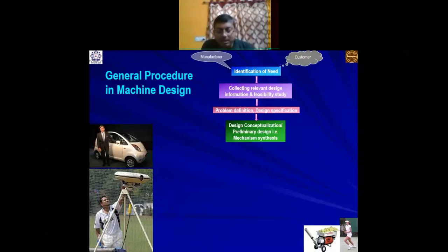Rolling mill means there are two rolls, with a gap between the two rolls. In this narrow gap, a billet is squeezed and passed through, and it is not a single stage but multiple stages, through which the billet gets the shape of a rod, channel or angle, whatever end product you need.